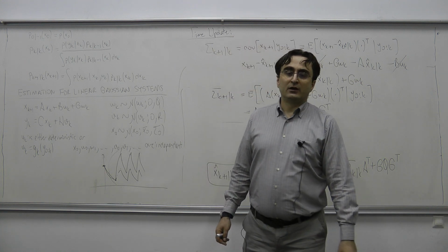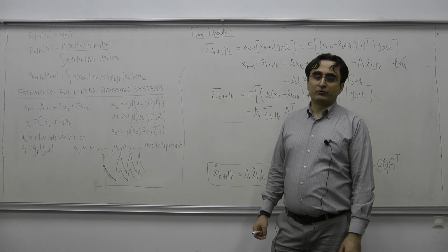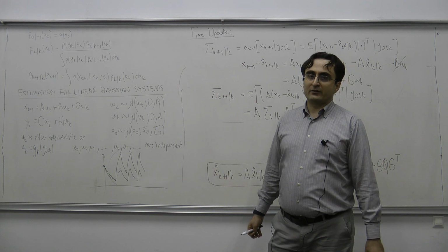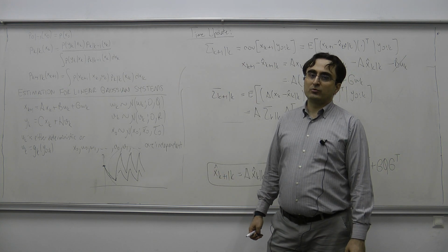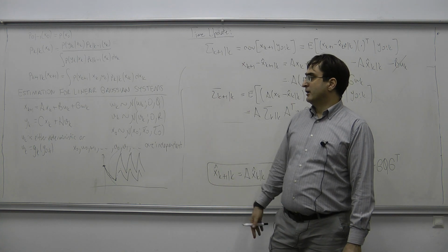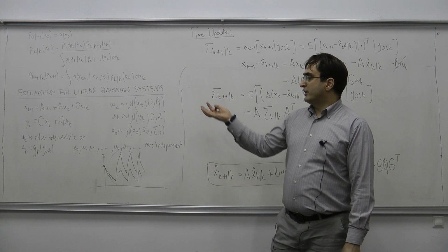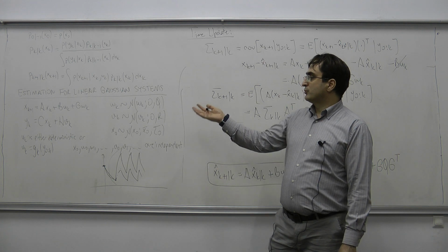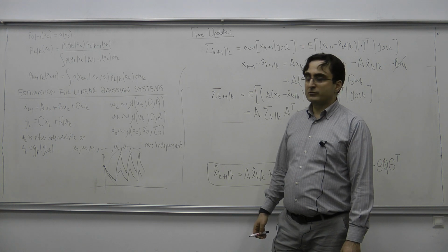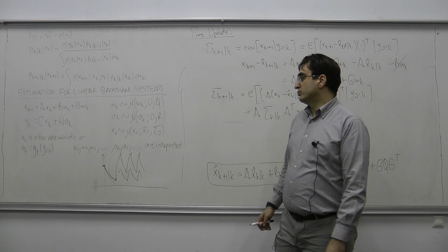Sometimes the covariance of the Kalman filter might diverge, and that is related to the problem of estimatability of the state. Or in control theory, we call it observability. So if your system does not have observability, we're going to see this in one of the next lectures, these covariances are not behaving this well. They're going to behave violently, and they might diverge to infinity.